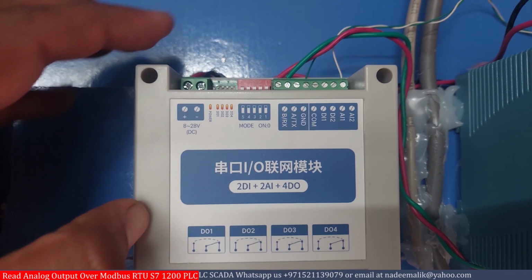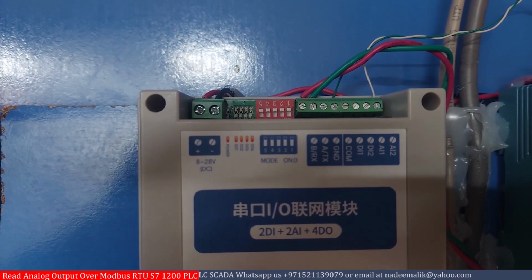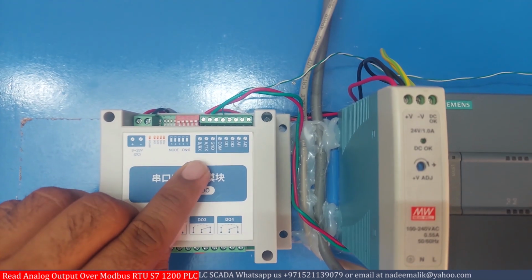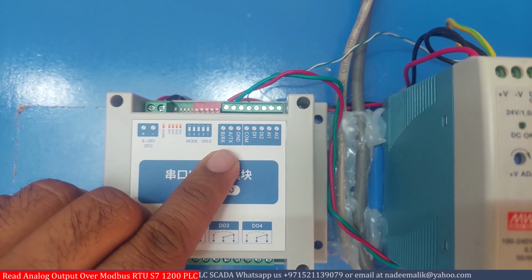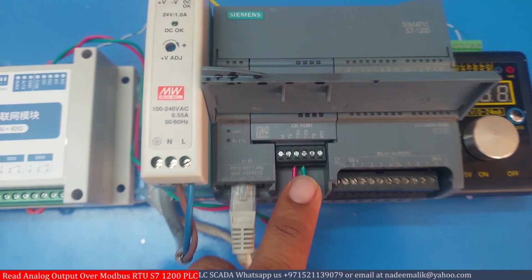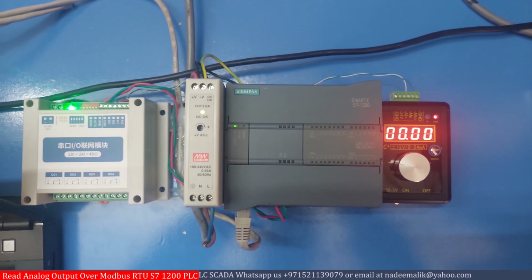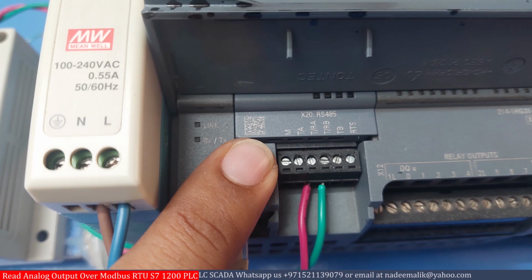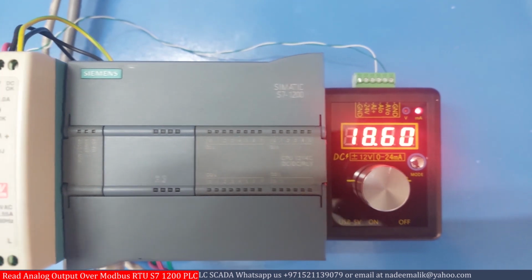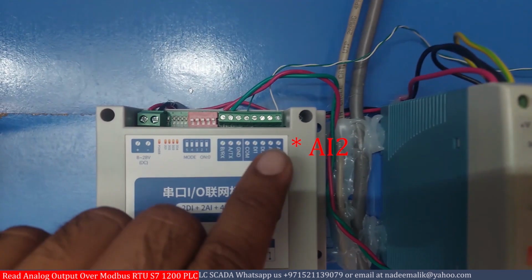The address of this module is 32. We set this address using these dip switches. As you can see, we have connected the A and B, RX and TX terminals of the I/O module with the RA and RB terminals of the RS485 port of the PLC. I have installed an RS485 communication card on the S7 1200 PLC. The part number is mentioned in the description. We have connected 4 to 20 mA signal generator wires at analog input channel 1 of this module.